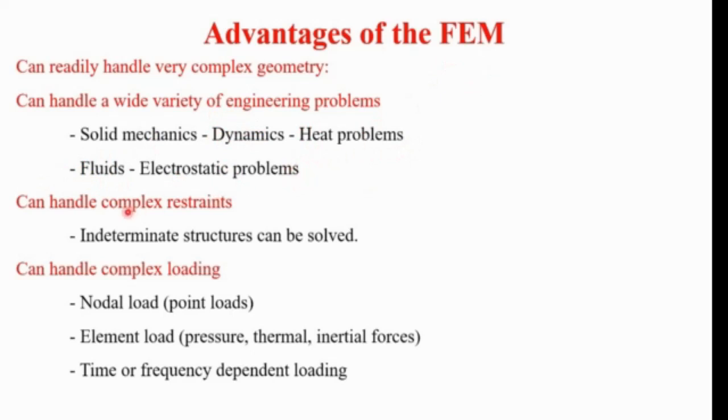Also, it can handle complex restraints, that means intermediate structures can be solved by using this method. Then it can also handle complex loading, for example a point load, or we can say a nodal load on an element, then elemental loads, for example pressure, thermal, and inertial forces acting on the elements. Time or frequency dependent loading can also be handled in the finite element method. So these are the few advantages of FEM.